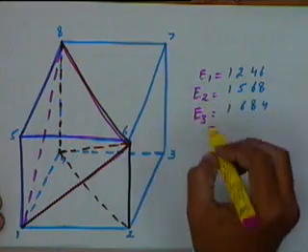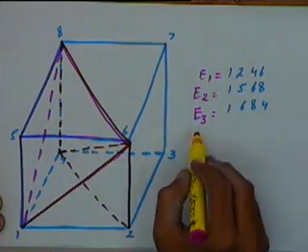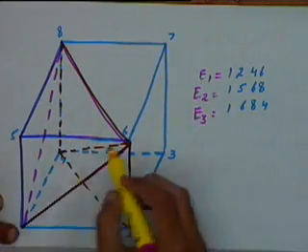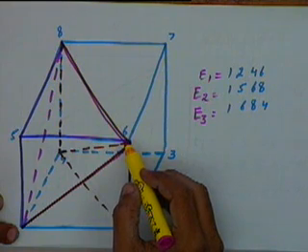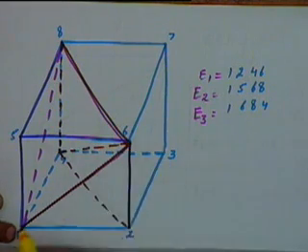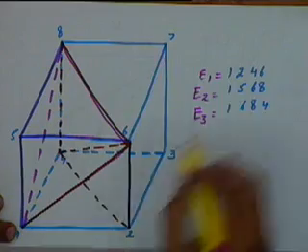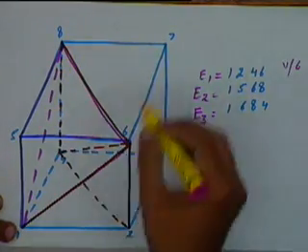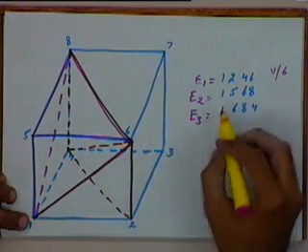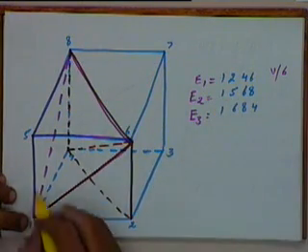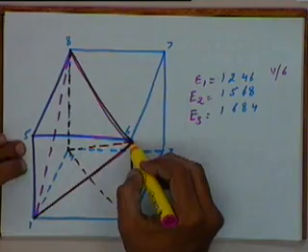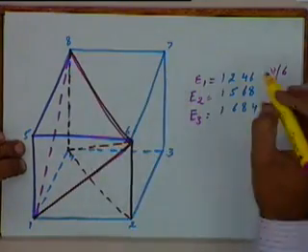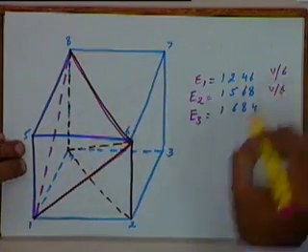In these 3 elements, if I look at the volumes of each of them, for 1, 2, 4 and 6, I can look upon this triangle 1, 2, 6 as the base and 1, 4 as the height of the pyramid. So the volume of this will be V by 6, where V is the total volume of the cube. Similarly for 1, 5, 6, 8, 1, 5, 6 can be looked upon as the base and 5, 8 as its height. So the volume of this will also be V by 6.